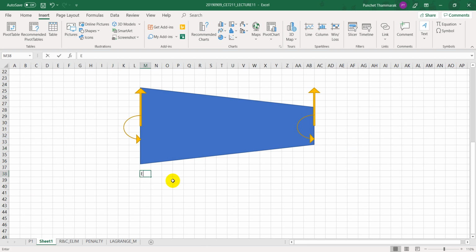I think we vary from 2 EI to 1 EI on the right hand side, and you evaluate everything, the rotational stiffness and translational stiffness. You have done it by the closed form solution, so you derive it and solve mathematical equations.